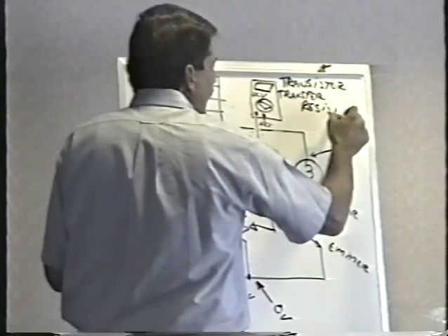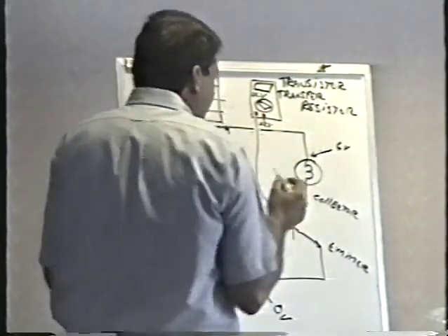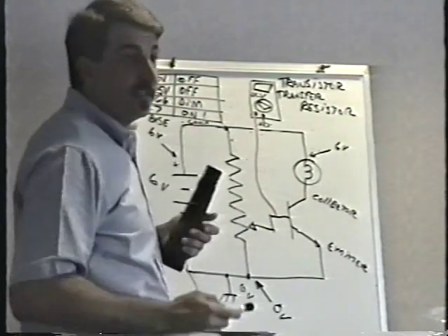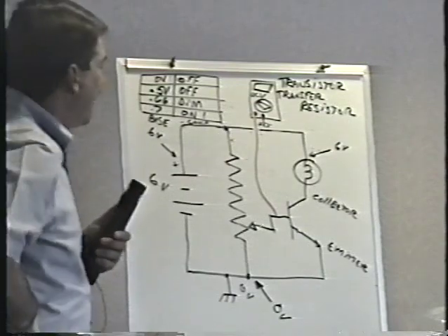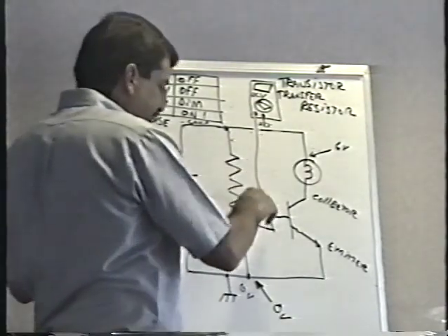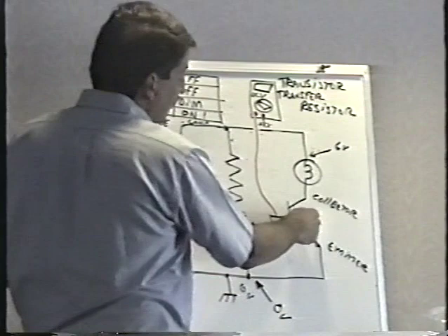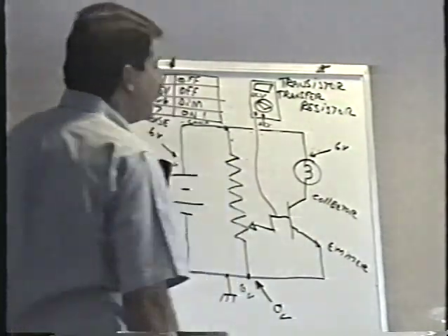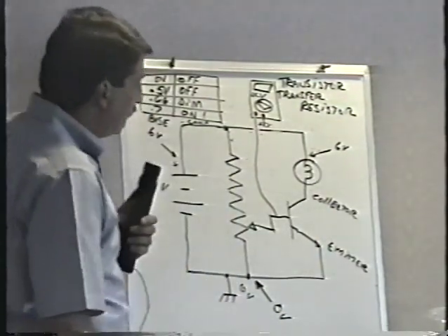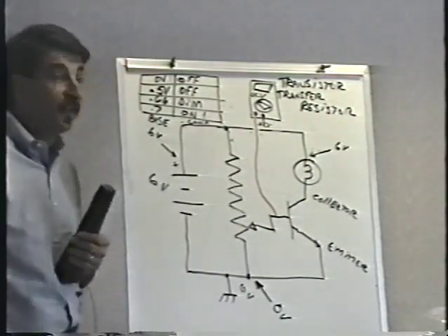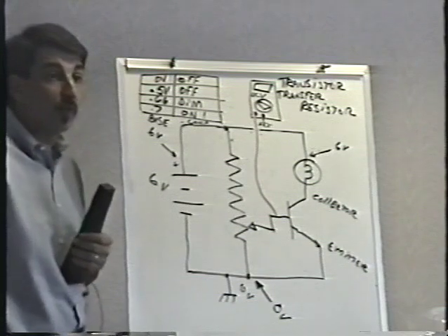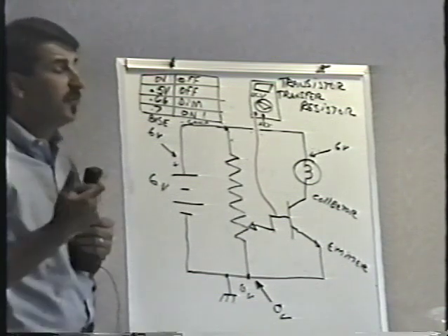You don't really have to know that, but that's what a transistor is. They didn't just make up the word transistor out of nowhere. That's where it came from, transfer resistor, as the change in voltage of the base is transferred into a change of resistance between the collector and the emitter. To be honest with you, it wasn't until I hooked up a transistor just like this that I really understood how transistors work. And there's really nothing mysterious about them.